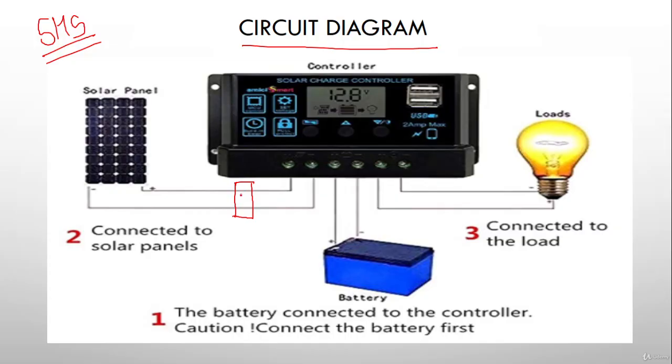The role of a miniature circuit breaker is that whenever an excess amount of current is passing, it will trip and safeguard our solar charge controller. So while joining the solar panels to the charge controller, in between we can use one MCB switch, or we can also use a fuse to save cost. Then we give connections to the PV panel.